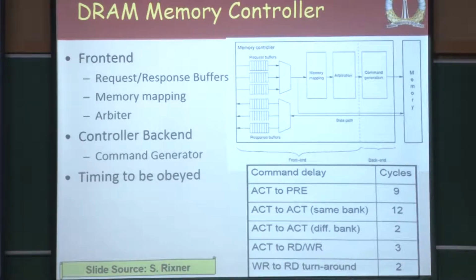And how many writes you can do in a window of time is also defined. So, there are many other constraints in the DRAM manual or the JEDEC standard, and the controller has to obey all of these things. It would take a lot more time to understand all of them. So, we will only do some of them here today, and that should give you a reasonable idea of how these DRAMs work.